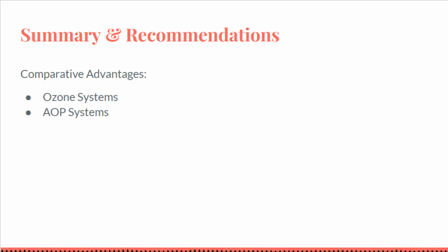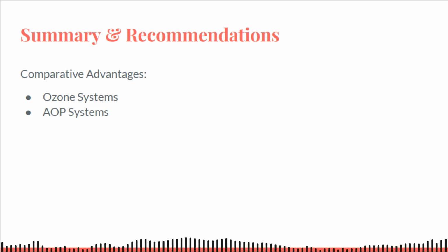AOP systems: cutting-edge performance by generating hydroxyl radicals, the strongest oxidizer available for pools. Achieves even greater destruction of contaminants. Some systems claim 99.99% pathogen reduction, and virtually guarantee minimal chloramines. Particularly beneficial for those with heavy pool use or health concerns, e.g. wanting extra protection against crypto or other chlorine-resistant microbes.